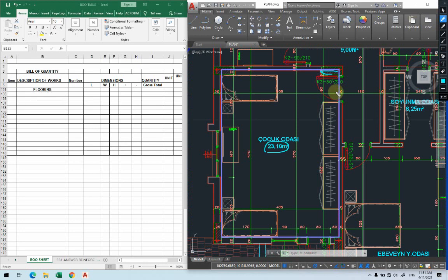If you use AutoCAD, you can calculate the area of the place that you want. But if you do it with the table, you have to take care of these small corners. As minus, you can write it. This is one. What else do you have to add? This is extra you're taking out of it. If it's tiling, you will add under the wall. But remember, under the wall, you'll add it only for this one here. You'll not add it for the other side as well. Because under the wall you have tiling going on, yes? So you have to cover that one as well.